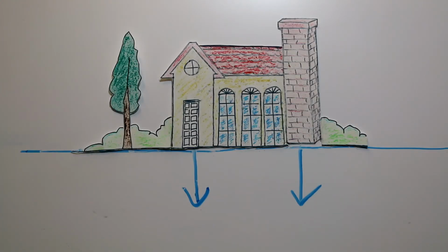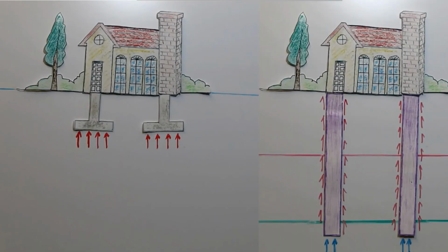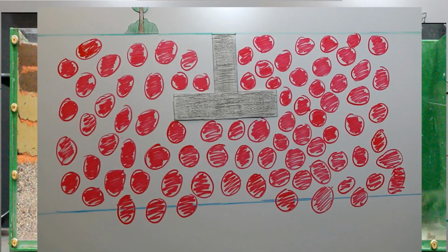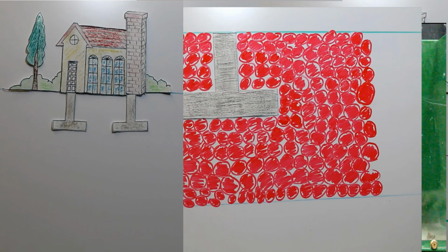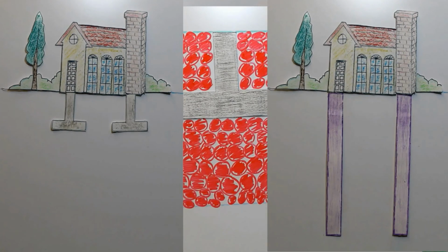When designing a foundation, it is important to take into consideration the reaction the soil will have to the type of foundation that will be used. If too much settlement will occur, one of two things can be done. The soil can be improved, or the type of foundation can be changed to a more suitable one. The strength and stability of a foundation is directly tied to its interaction with the soil around it. Good engineers recognize this fact and are able to design an appropriate foundation for every site.